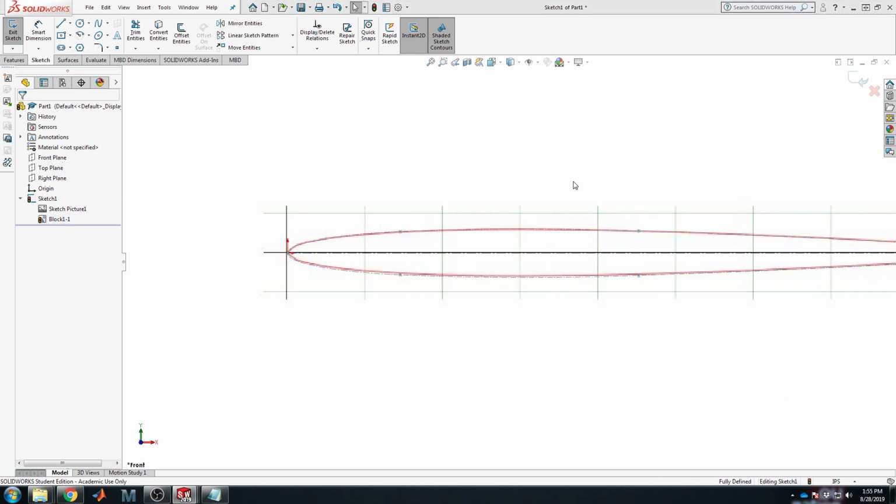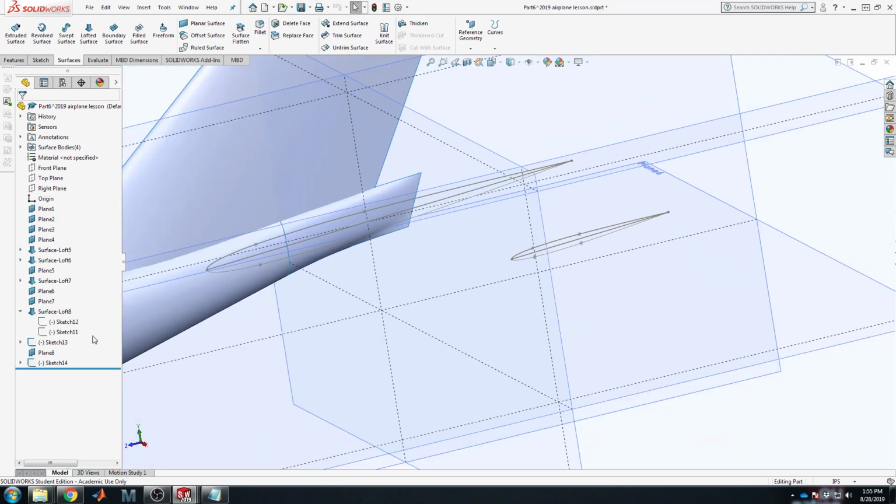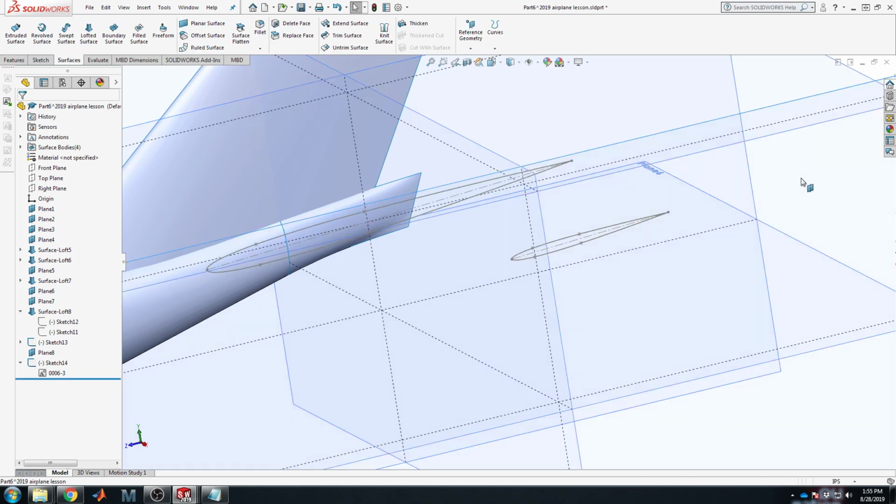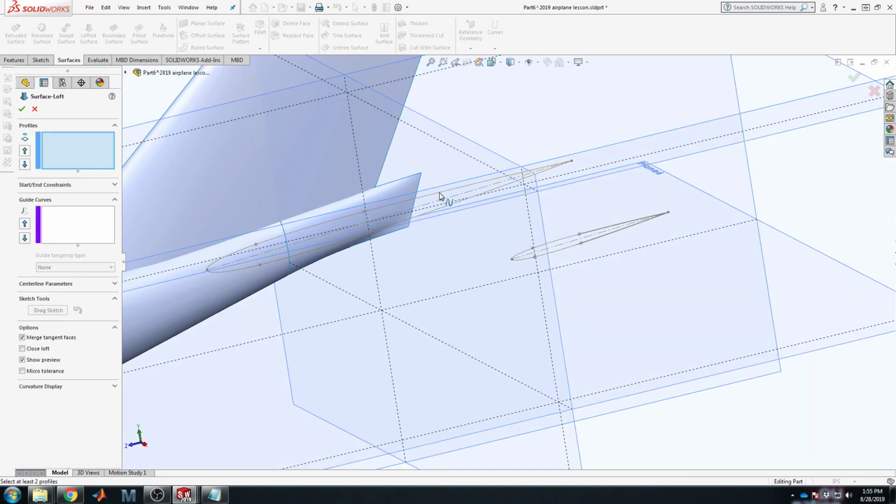Now this will be an interesting question. Will it automatically update over here? No, that's unfortunate. See if we can edit this block real quick. Should be easy. Change it one place, it'll change in the other. To turn that to construction geometry. Exit the block, exit the sketch. Now we should be able to loft it much more nicely.